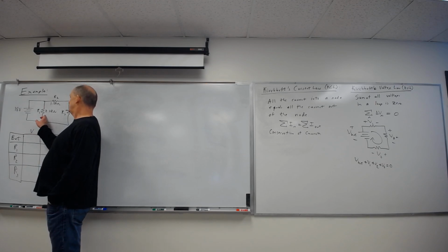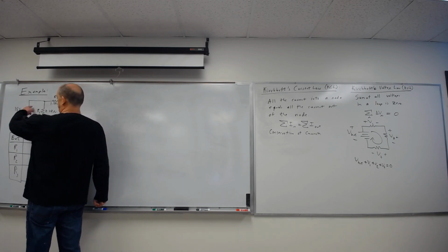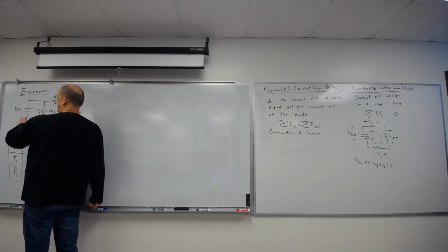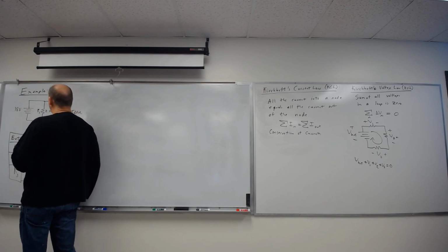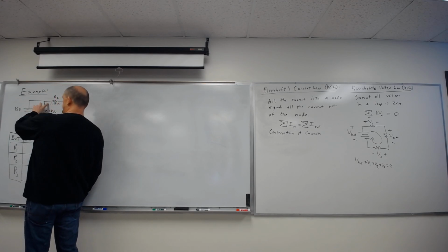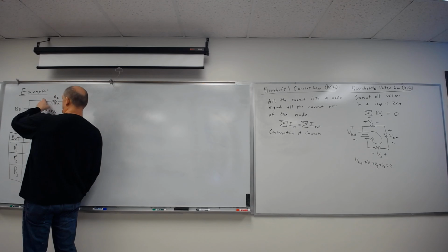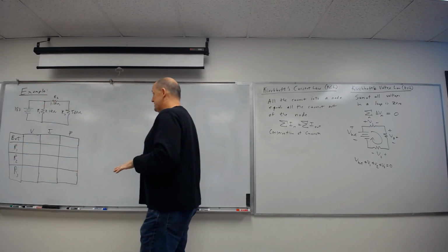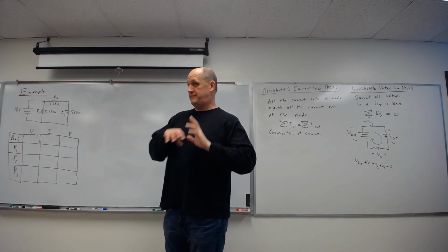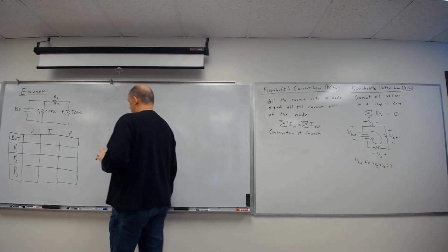That's just series. Not series, parallel. The two ends are connected to the two ends of this, so this will have 18 volts across it. And then I would find the current. So this is in parallel to the battery. These two are in series with each other, but the combination from here to here would be the same voltage as the battery. So again, the easiest place to start is probably to go furthest from the battery and work that.